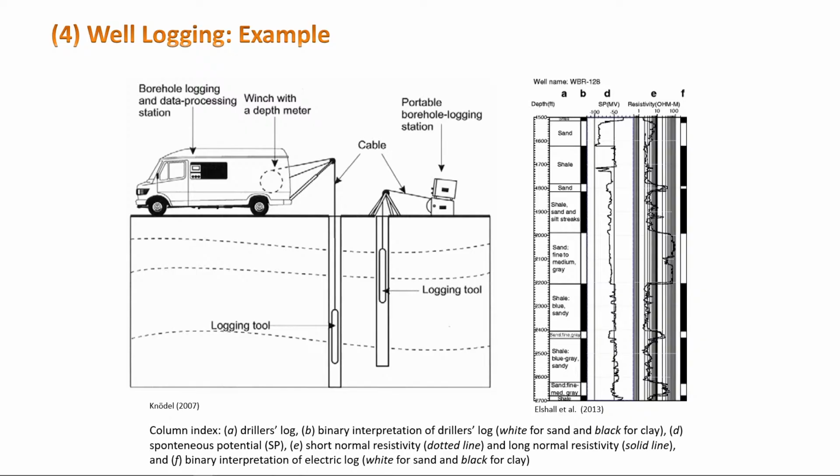The driller will give you two things. The first thing he will give you is the drilling log. With the drilling log, he will tell you, as I was drilling, I found sand from this depth to this depth. Because as he's drilling, the material will be coming out. He's drilling out the material, so you can hold it and see what it is.